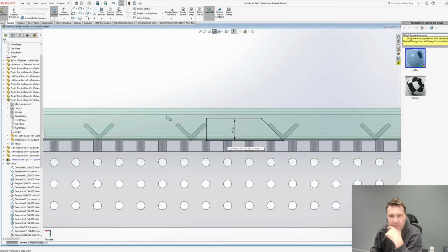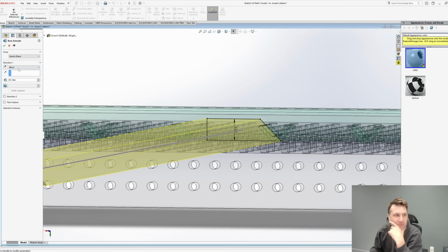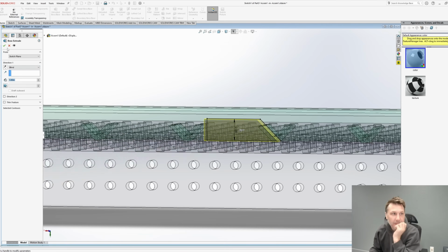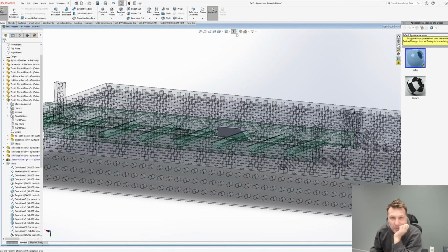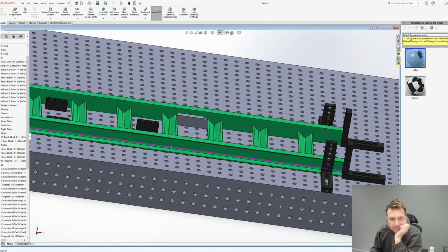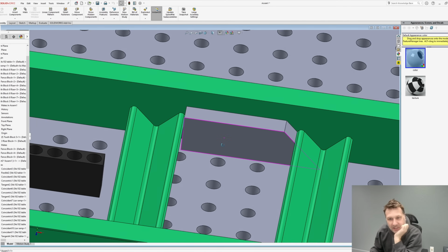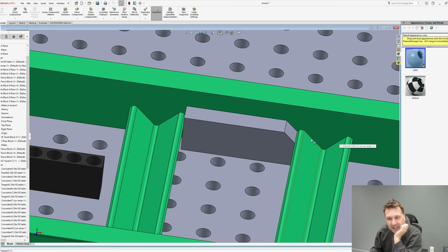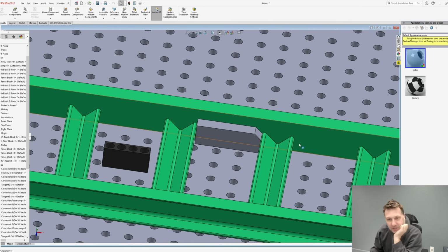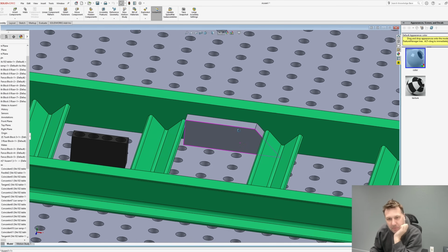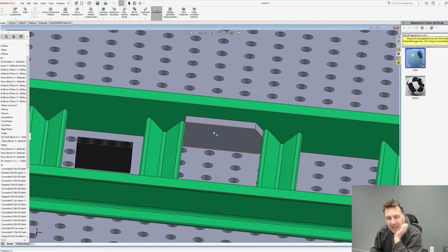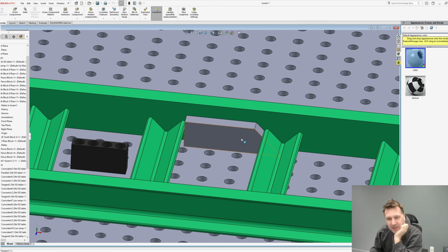So there we go. Now we got our own little custom spacer block, and then we can jump this block down the line. So let's extrude this out. So let's do it 1 inch. There we go. And let's get back to normal. So something like this would work. And the problem is getting this out. That's kind of why I have this over here, so we can kind of swing it and get it out of there. So you could tack, move this block or print 2 of them, and then jump to the next one and go tack. The problem with a custom fixture like this is you might have what I like to call stacking tolerances. So that may not be the best idea.